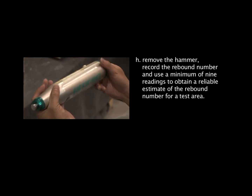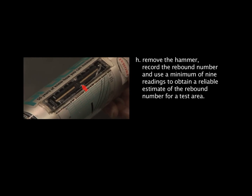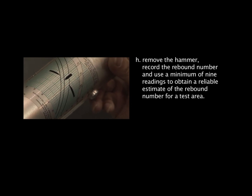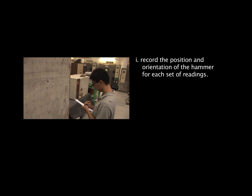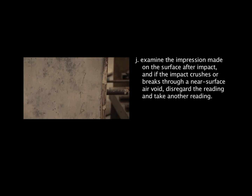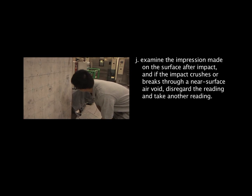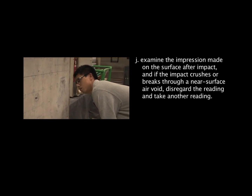H. Remove the hammer. Record the rebound number and use a minimum of 9 readings to obtain a reliable estimate of the rebound number for a test area. I. Record the position and orientation of the hammer for each set of readings. J. Examine the impression made on the surface after impact, and if the impact crushes or breaks through a near-surface airvoid, disregard the reading and take another reading.